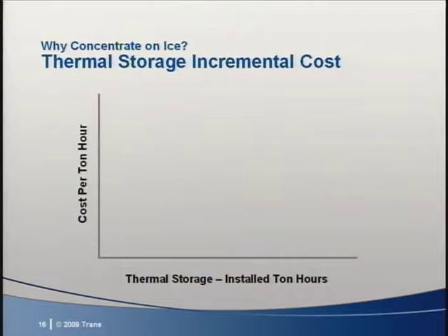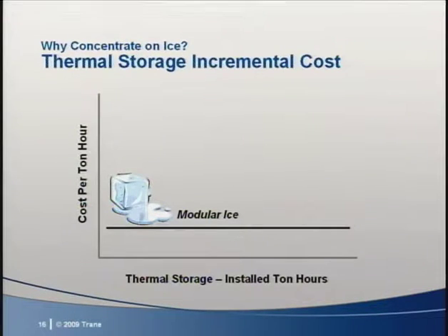One final comment in this Why Thermal Storage section. In the introduction, Jeannie told you this broadcast was going to be focused on ice energy storage. You may be asking, why not chilled water storage? It is absolutely driven by market applicability. Because of the storage volume requirements, ice energy storage is most often supplied using prefabricated modular tanks. This has the impact of providing a relatively low and linear installed cost per ton-hour of storage over a wide capacity range, as depicted in this chart. This helps make ice economically feasible for many building types.